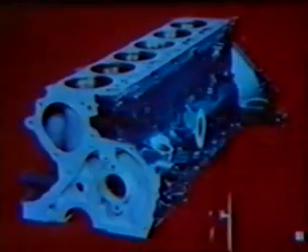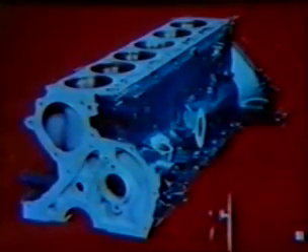With that identification of the system components and functions, let's look at the pieces one by one, somewhat in the order of building the engine up from loose parts. The cylinder block is the main supporting part of the engine. It is usually made of cast iron, with the cylinders machined carefully for true roundness and square alignment with the crankshaft.